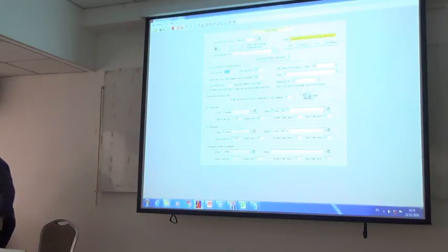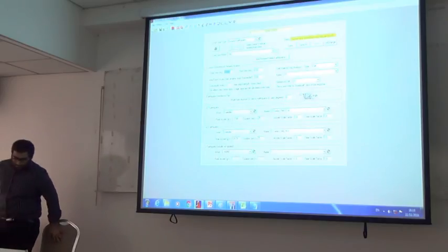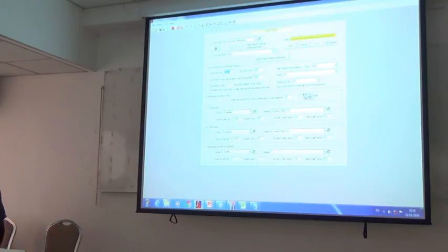If we have secondary beams in the model, which are resting on the main girders, in the Perform 3D model it is better not to model the secondary beams. Because if we model the secondary beams resting on the girder, we have to physically divide the girder in the model. So when we apply the hinges on the divided girder, we have to apply one at the left end and one at the right end only. So it will be complicated when you create the compound section and assign it on those girders. So for the secondary beam, we just apply a point load on the girder to represent it.